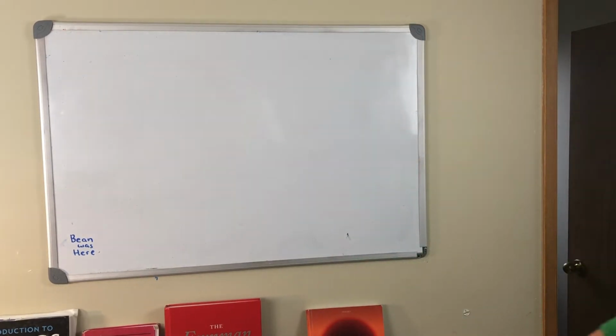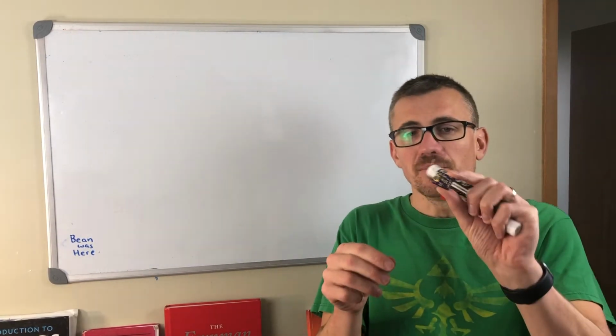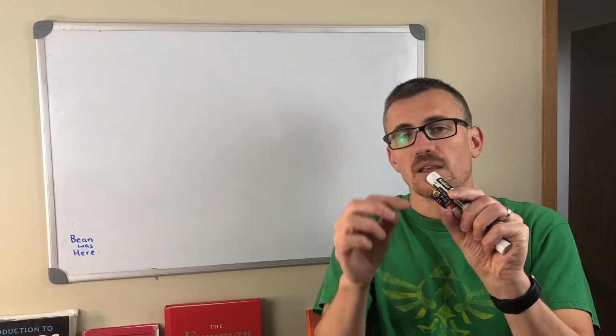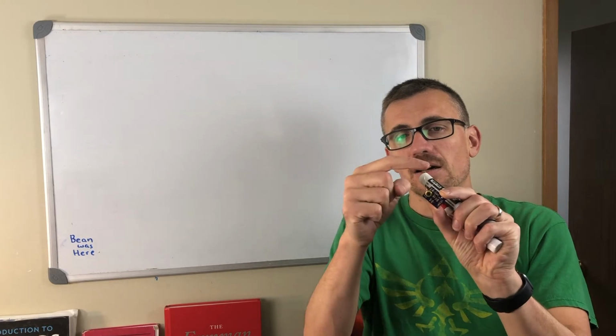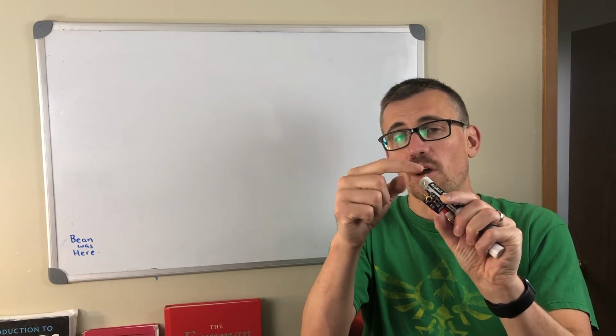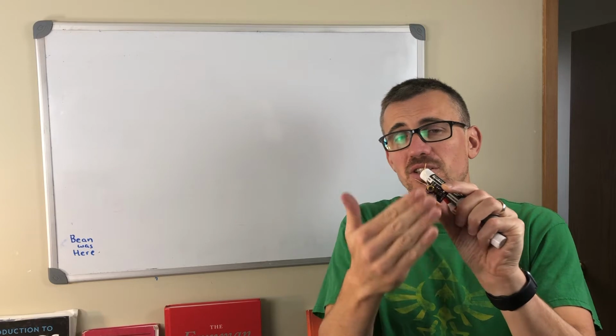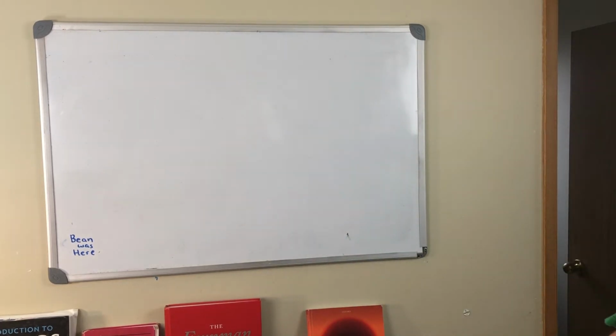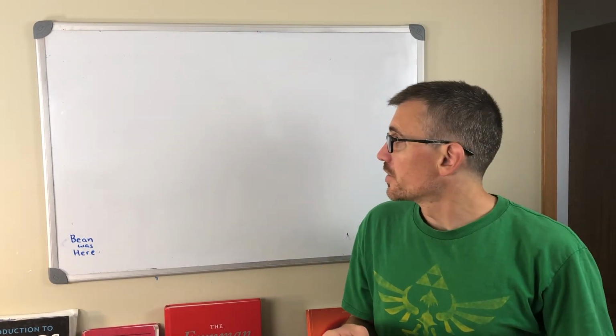So again, I have some circuit here. If I just put wires out between 2 points on that circuit, I can plug in a load resistor or anything I want between these 2 points, and the rest of the circuit is just going to look like a single source and a resistance. And that's the idea of the Thevenin equivalent circuits.